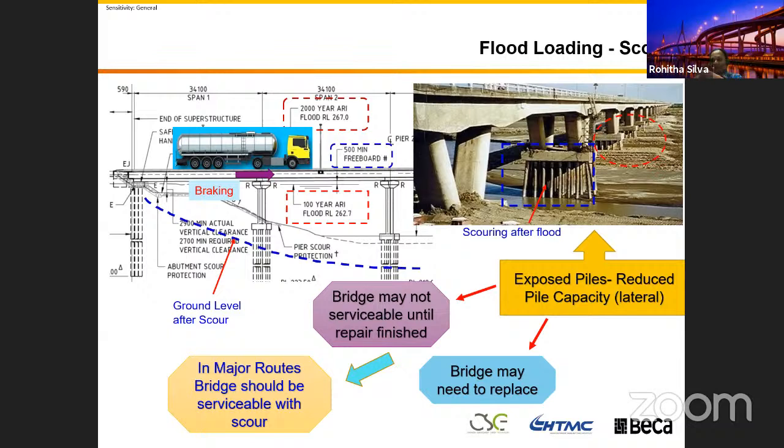So they are going to be subjected to significantly large longitudinal load, again depending on the way the geotechnical engineers design the pile. If you have significant scour in your bridge, you will lose a lot of the capacity as well. You can see in this particular bridge, I just drew what the ground looks like after a significant flood event.